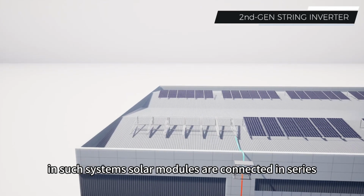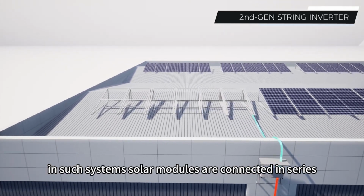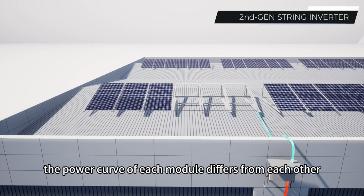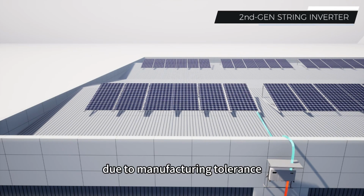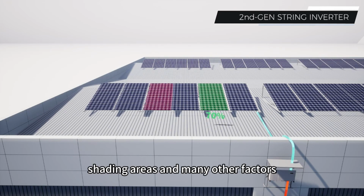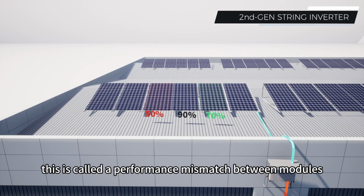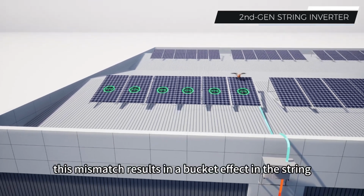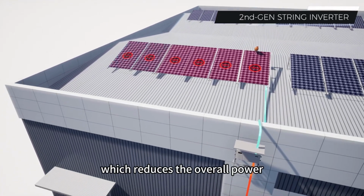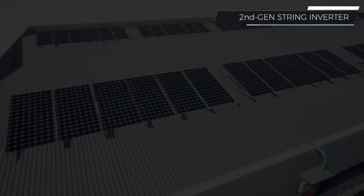In such systems, solar modules are connected in series. However, the power curve of each module differs from each other due to manufacturing tolerance, installation differences, shading areas, and many other factors. This is called a performance mismatch between modules. This mismatch results in a bucket effect in the string, which reduces the overall power output of the entire system.